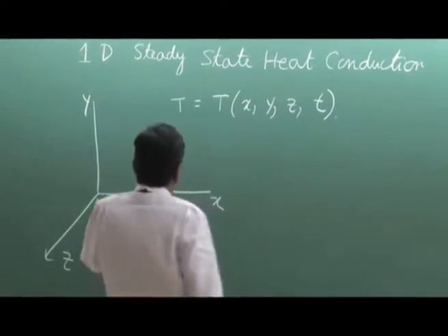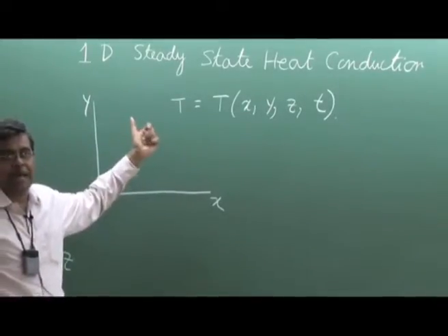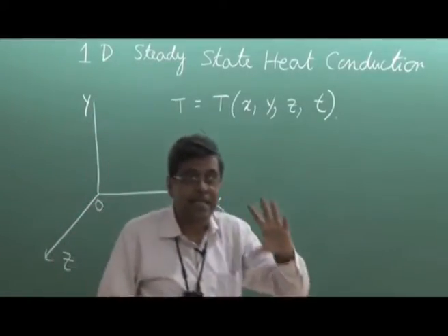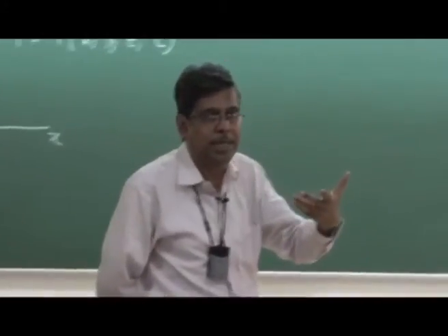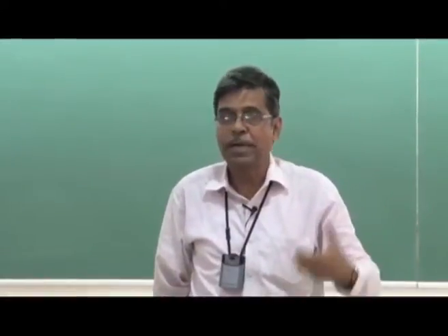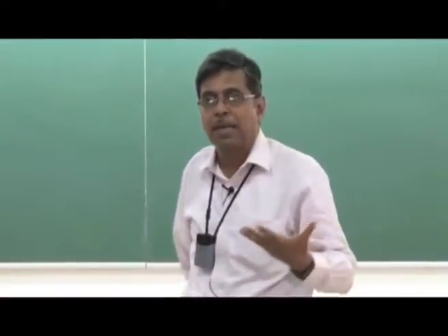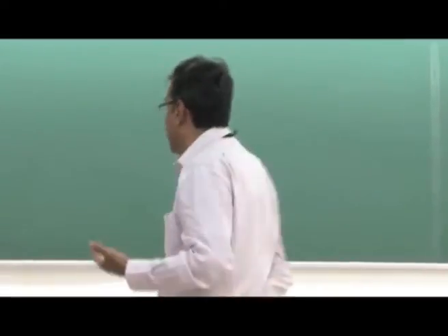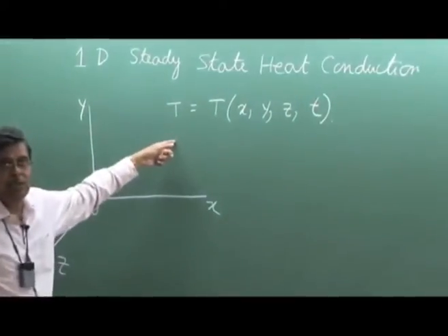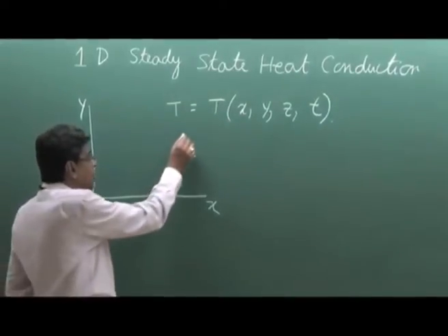Now, along with that, it may so happen, after our observations in practice, that there are several conducting systems which, while conducting heat, generate energy, which colloquially we call generation of heat, but they generate thermal energy because of some chemical reactions or by any other action. Sometimes they absorb thermal energy. So generation of thermal energy is also very important, so we also took care of this generation of thermal energy in deducing the differential form of the expression.